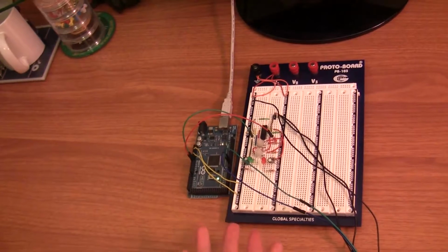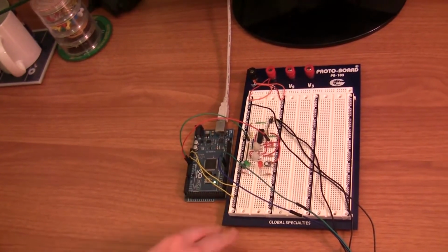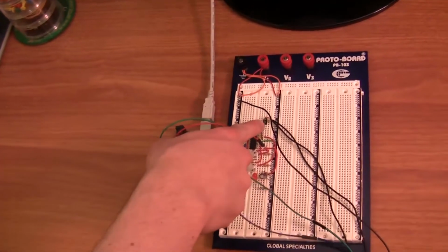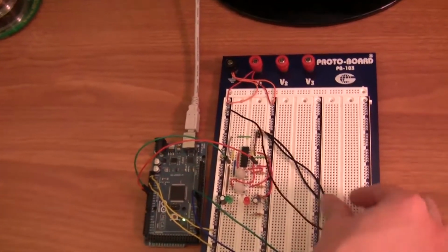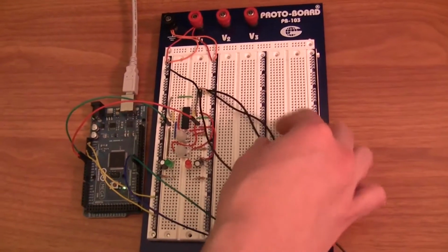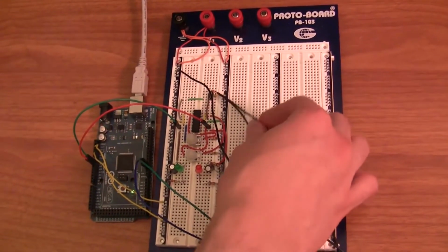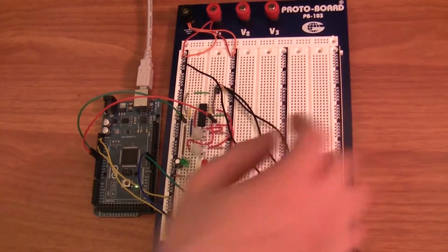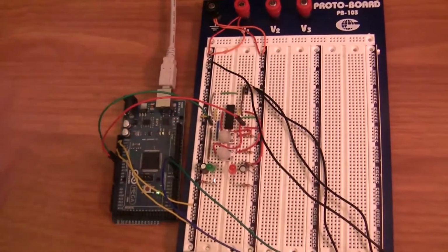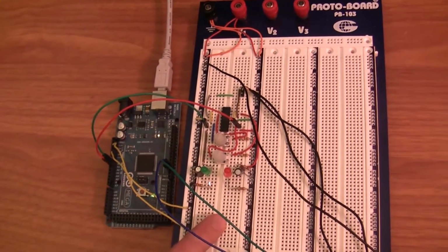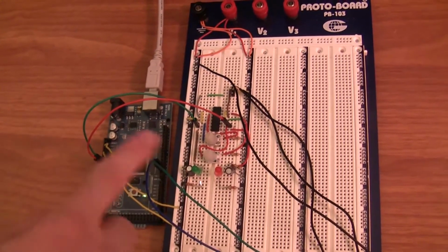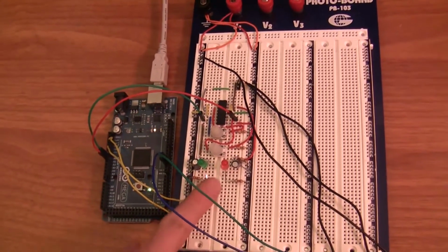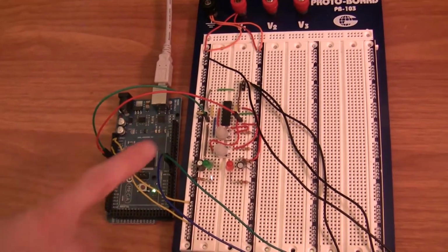Okay, so here we have the circuit all wired up, just like Brian showed in the schematic earlier. First and most important thing, we have our audio signal coming in at the top here. Basically, we've taken apart a pair of old headphones and used 2 wires to bring them in here. Each wire from the headphones, the left and right, has a channel and a ground. So you need to bring in both channels and just one of the grounds and make sure you hook it up into the ground of the rest of your system. And don't forget, I know this looks complicated, but you'll be able to download the full schematic and breadboard view from my website. The link is in the description.